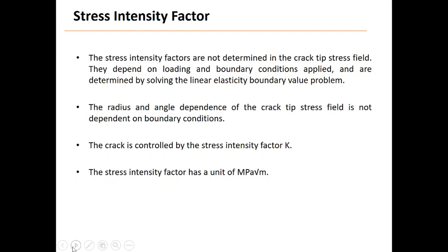So the whole problem of fracture mechanics boils down to finding K, measuring K, and making sure K is not beyond what the material can resist.